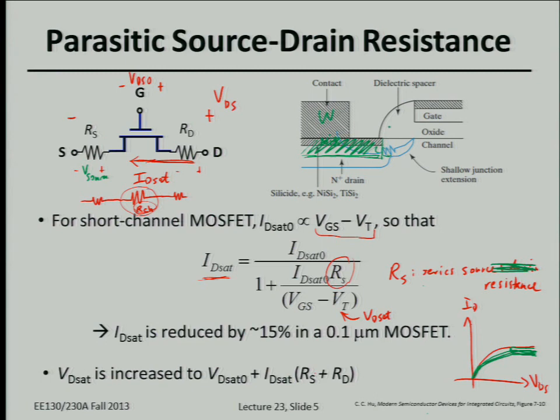You can't aggressively scale down the depth of that p-n junction, or you can't overly silicide the junction. So actually, in maybe only the most advanced technologies today, they're starting to eliminate the silicide, because the junctions are getting so shallow, there is no space to form a silicide. Okay.